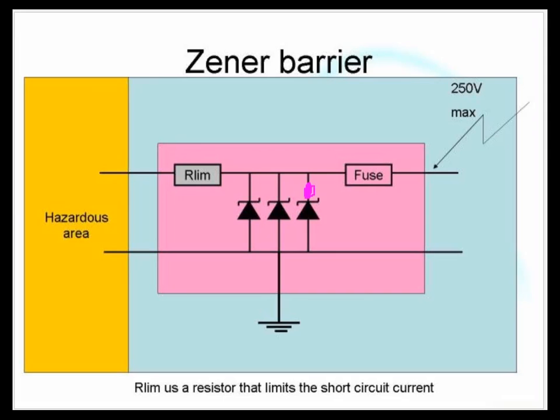So every now and then, after you've, for instance, tested it, one of the Zener diodes is dead. And then maybe a little while later you might test the second one, and the second one might not recover. So we have 3 on there for safety, because you're probably going to blow the first one up when you do install and you test it the first time. You're probably going to blow the second one up the next time it gets used, which leaves you 1 as a fallback.